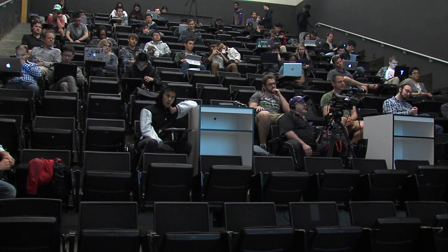Okay, yeah, I should be restating questions because we're being recorded here. So the question, at least from what I perceived, is how is it that these things are able to all take on behavior at this particular frequency when they don't know of each other's existence? And how do they do this? The reason this works is because we program them all with the same resonant frequency. So even though there are separate DSPs or FPGAs for all of them, we program them with that same resonant frequency, and that is enough to give you this behavior.